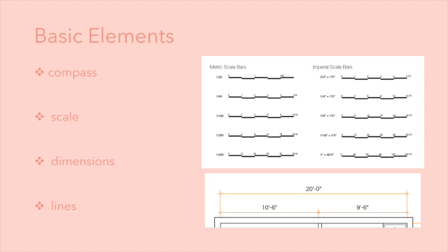So as the numbers in the scale get bigger, the second number here that's shown on these scale bars, the elements in the drawing get smaller, and that's because the larger the number is, the more is represented by one unit in your drawing. So for example, this one unit here, I don't know if you can see my mouse, hopefully you can. Let's say it's a centimeter. This 1 centimeter here represents 500 centimeters in real life. So obviously 500 centimeters squished into 1 little centimeter is a lot smaller than 20 centimeters would be squished into 1 centimeter on a page.